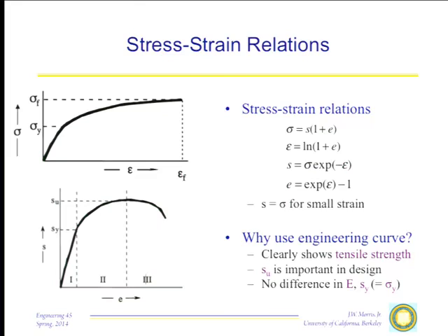So given that this curve is real, this one is not, this one is physical, and it's fundamental in its variables, this one is not, and the two curves look very different, why on earth does everybody tabulate this one instead of that one? Very simple reasons. Handbooks of data are produced for engineers, not for fundamental scientists. If you're an engineer designing a building or a bridge or something of that sort, you end up really caring about two things. One thing you really care about is the elastic region back in here, because almost no engineer ever designed something to operate outside its elastic region.